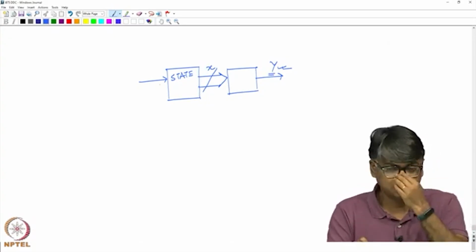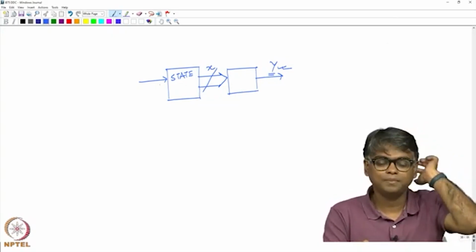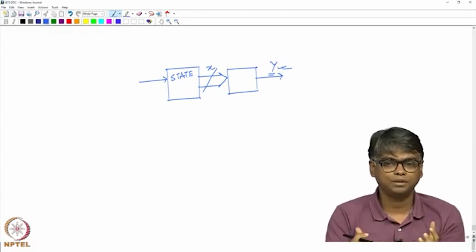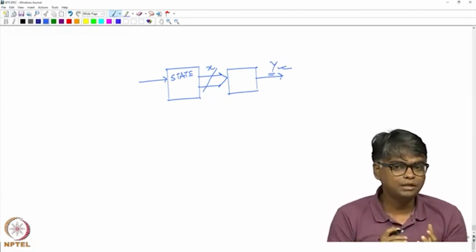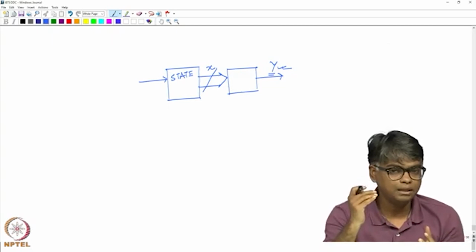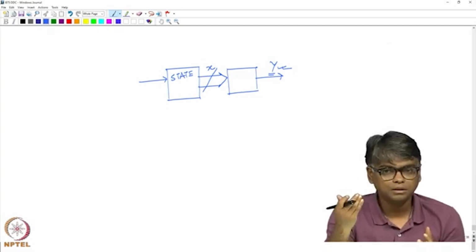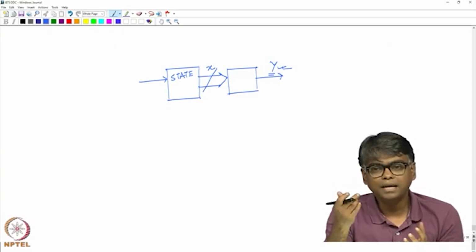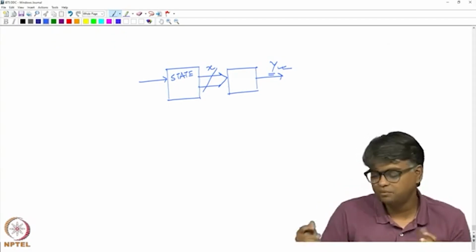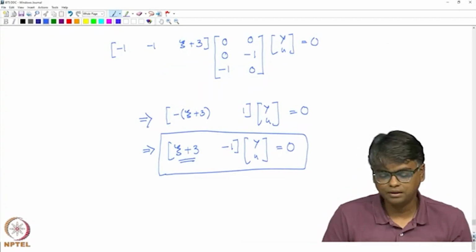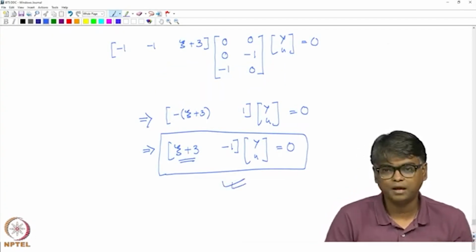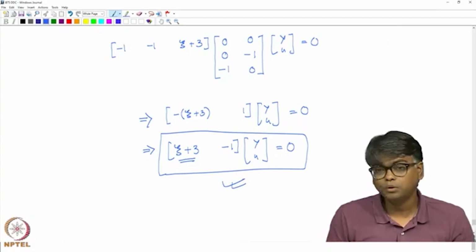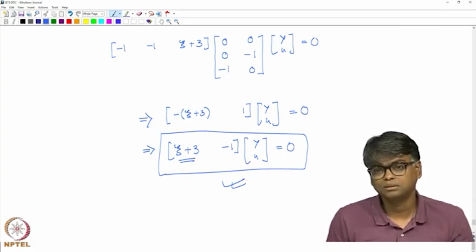So, whether it was controllable or not, that does not really matter, because it was controllable if the input was affecting both the states, right. But input cannot affect the Y as well as its derivative, both these state variables, because Y has only first order dynamics. That is why when we get the manifest behavior, we have only a first order dynamics involving Y. So, then is it okay to do the pole 0 cancellation or not?